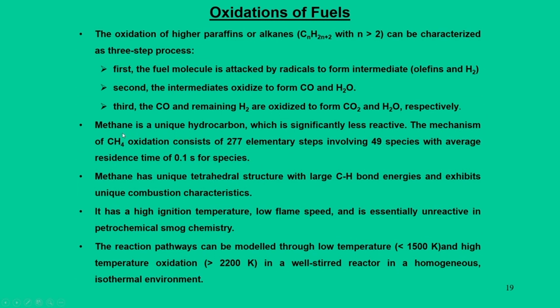In fact, we are not going into details, but a simple hydrocarbon is nothing but methane, and it is a unique hydrocarbon, and it is less reactive. But even though it is less reactive, it consists of 277 elementary reactions with 49 species, and 0.1 second residence time of each species. That means it forms and then gets destroyed. So, the residence time of each species is, on average, about 0.1 seconds. And methane has a tetrahedral CH bond energy, which gives very unique combustion characteristics.